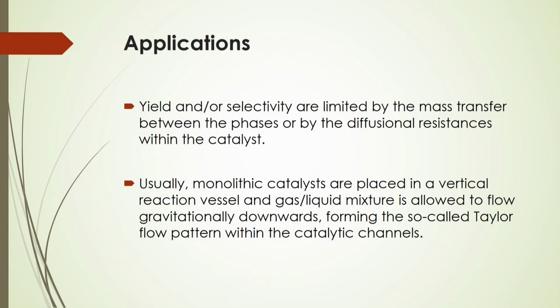So, in that case, hydrodynamics-based design of monolithic catalytic reactors should also be developed, so that you get a suitable flow pattern for the reactions, like in a honeycomb structure monolithic reactor. There you may get the Taylor flow pattern. That means slug-type flow patterns will be there, elongated slugs will be there.